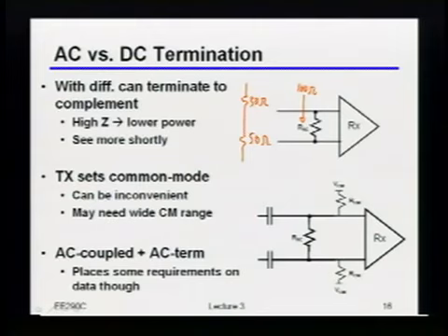Hook up the midpoint to... What do I hook it up to? Whatever common mode you want. Okay, so now, let's say I really do hook it up to a voltage source, which is V common mode. What impedance am I dealing with now? 50. I'm dealing with 50 ohms, right? Not with 100. So how do I still deal with 100 ohms? Say that again? Okay, well, I can put a large resistance, but if you put a big resistor there, then the bad news is that you're basically open-circuited and it doesn't really look like a common mode termination anymore.